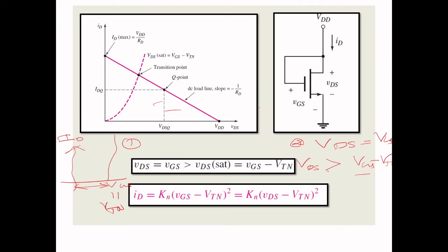So that means when you short your drain and gate, your MOSFET is forced to work in the saturation region. Okay, so that you get the functionality of the current source using active elements. So you can replace your resistor. Usually we connect some resistor to generate the current source, right? So that can be replaced with your active devices.